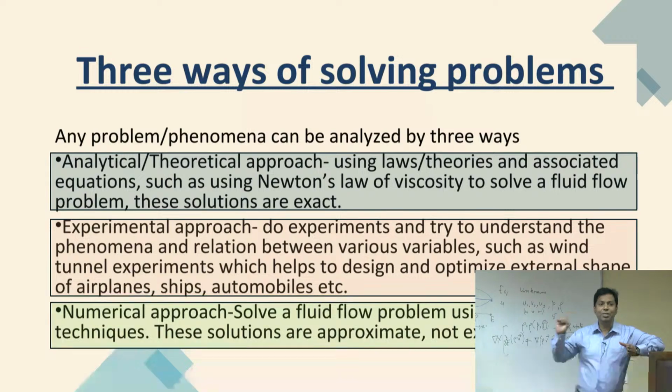So, at that time we can ignore the advection term, and then we can use the unsteady term balance with the diffusion term. This is the way we can actually get some solutions of velocity, some steady state time, this kind of thing. Mathematically it is a very algebraic equation we got at the end, but it is very quick, and the result is very accurate to one order of magnitude. And after that we actually validated our result after solving the full set of equations.